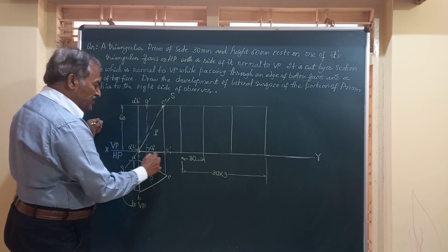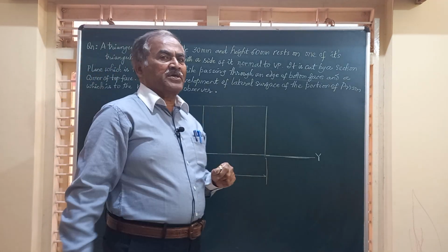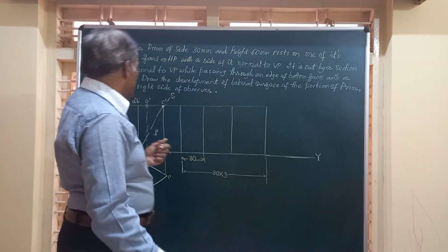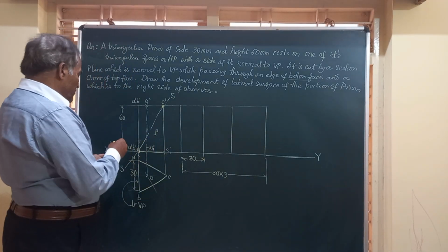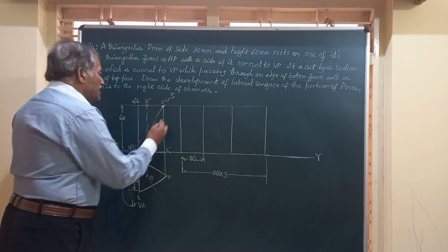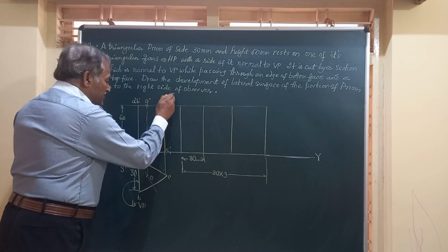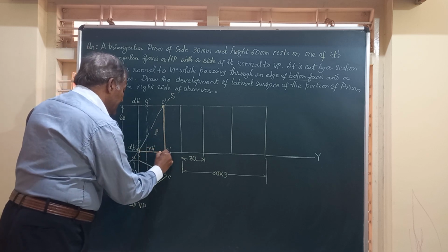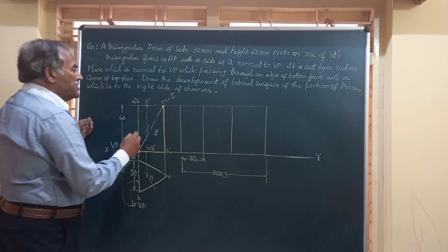So P is the triangular portion which is retained for developing the solid. So friends, after getting this section plane, we have to darken that portion of the solid that is retained. So this part is retained, and I should get the development of this part P.